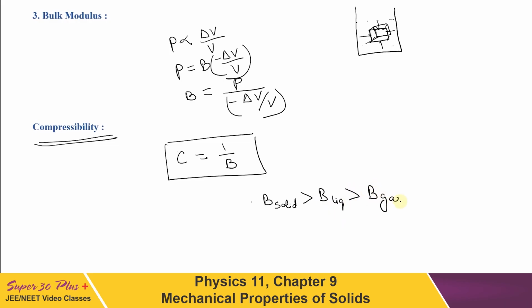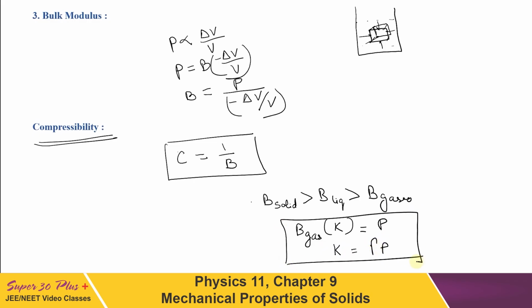We denote bulk modulus of elasticity with K also. For gases, the isothermal modulus of elasticity, either we can write B or K, is equal to the pressure of the gas. But this is only for isothermal processes. If the process is adiabatic, then for gas, this K can be written as gamma times P. We will see this later also in coming sessions. Till then, you have to simply memorize this value. So if a question comes which uses this formula, we can make use of it.